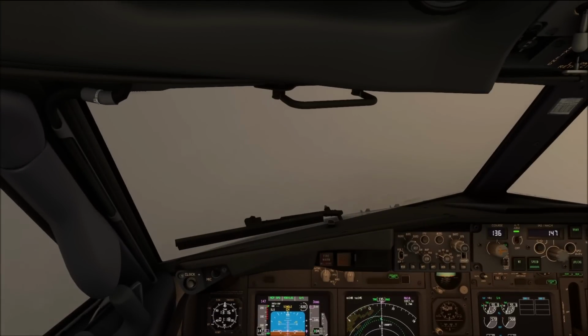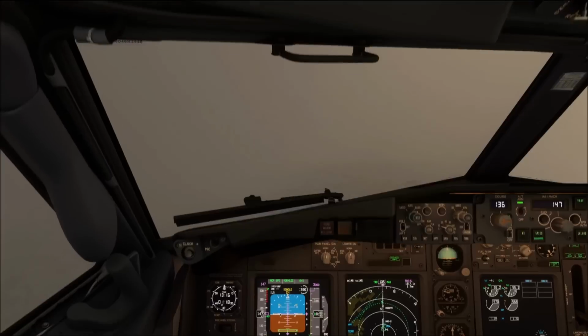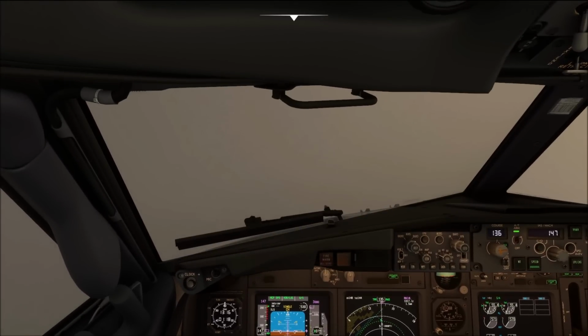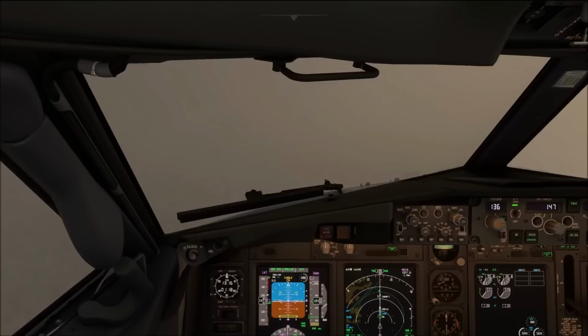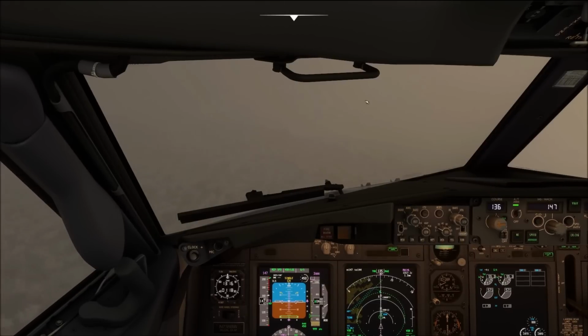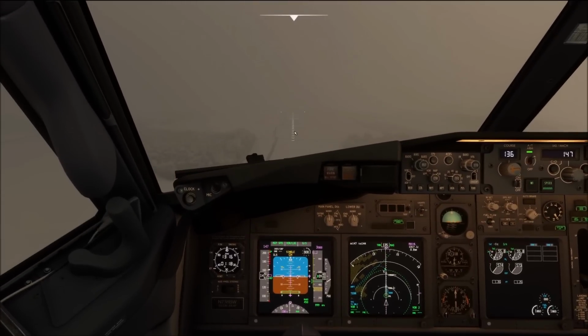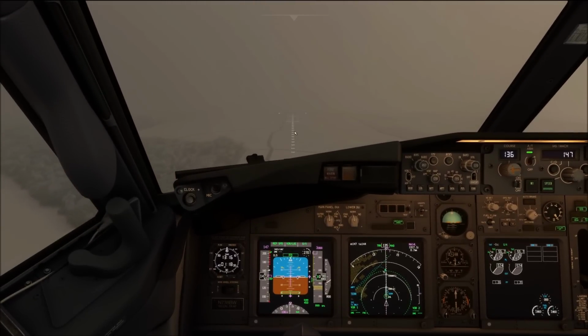In snowy conditions, typically the visibility is greatly reduced, so being able to see a runway early is something that you really should put an emphasis on. By selecting a little bit higher height for your view, or in real life by just putting your seat into a higher position, you can really help achieving this. Okay, approach lights are in sight. Plus 100. Disconnecting. Continue.